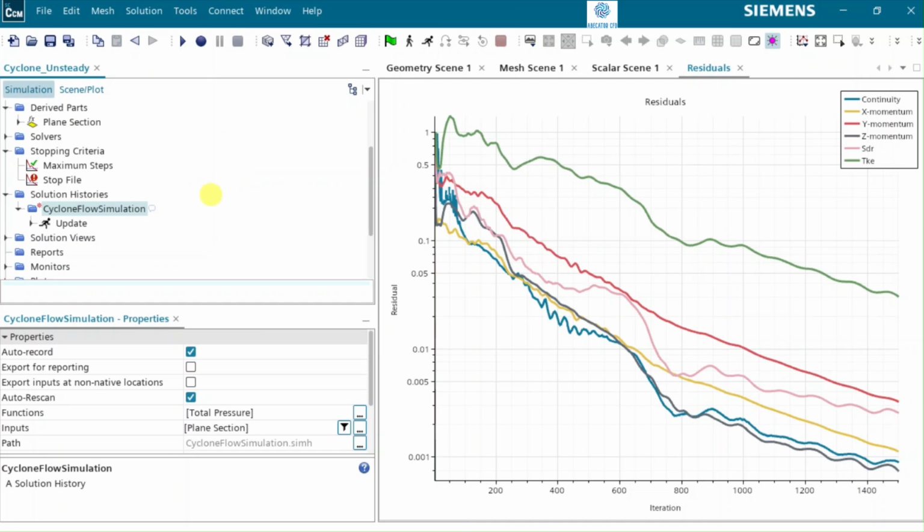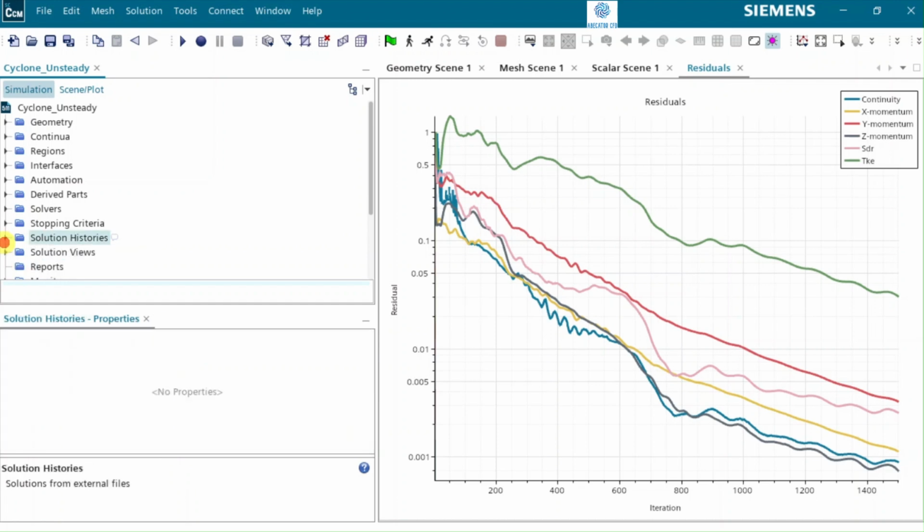Now comes one of the most important parts of the tutorial, switching to unsteady flow with curvature correction. Inclusion of curvature correction improves the turbulence model accuracy for strongly swirling flow like this, but once you enable it, a steady solution is no longer enough for proper convergence. That is why the case is first run in steady mode, and only then converted to unsteady mode.